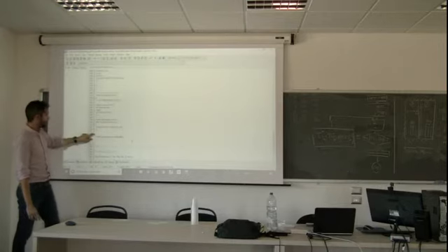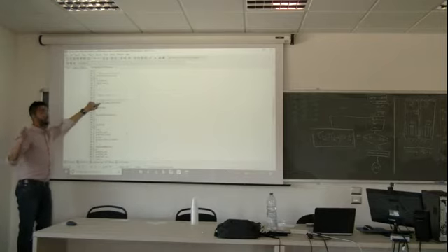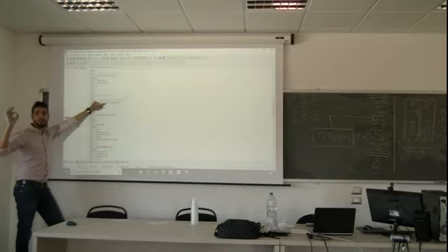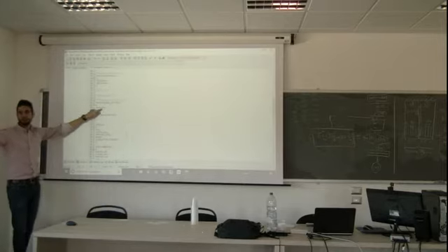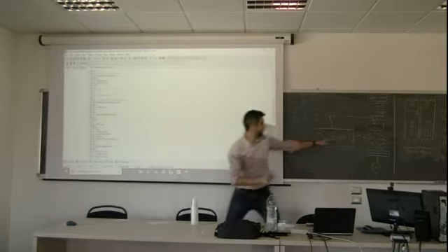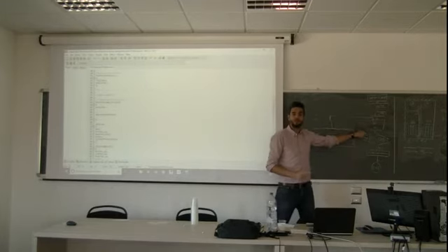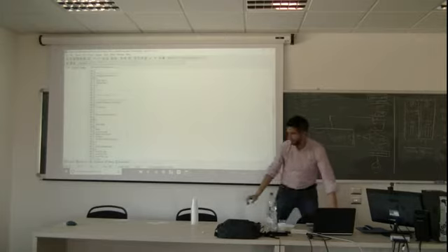Okay, now it will go here. If it's not the break, now we have a new map of assumed temperatures. It will go to the loop and say, J, we are in the first, J equal to 0 in the first iteration. Is 0 below maximum number of iterations? Yeah, maximum number of iterations is 1 million. You will have to run. Okay, J equal to 1. Now, we reset error total and explore again the domain and the equations. We are doing this with the new assumed map. Clear? Yes? Any question? Good.